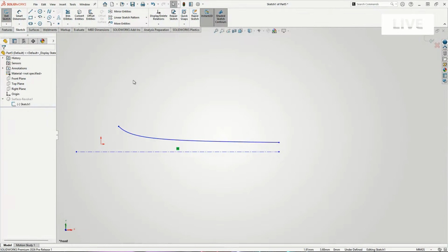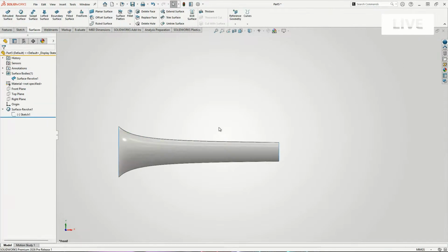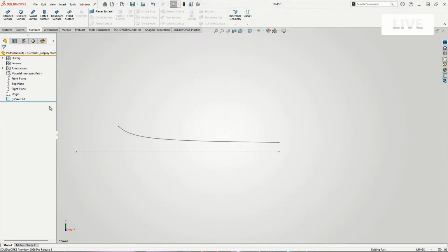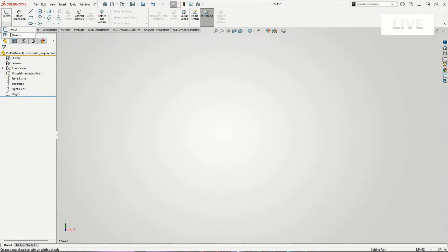Okay, so that's cool, but where it really gets fun is being able to do 3D driven parametric equations. And this isn't as intuitive to find. So what I wanted to show is how we can create some fun spring shapes, more kind of artsy style, I guess. I don't know, the engineering application, I'm sure if you think about it, that could be out there. So here's a trick. If you want to create a 3D curve, you need to create a 3D sketch. You can't start on a plane. So that's it. That's the secret sauce.